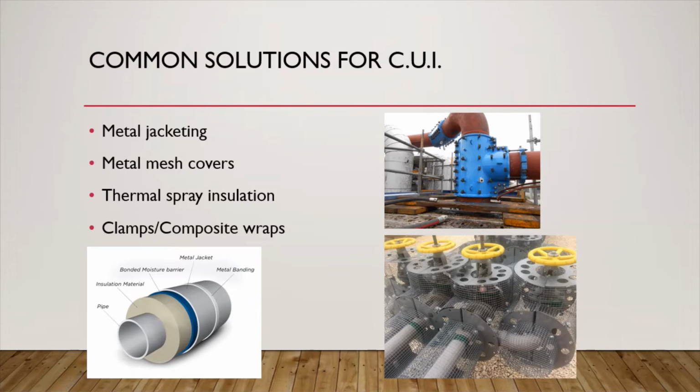Thermal sprays to coat the piping like a paint job are also available to use, but are significantly more expensive and are only used for more justifiable occasions. If the section of piping cannot be brought out of service for maintenance, then clamps, leak boxes, or wraps are usually installed to mitigate any leaks that formed or might be forming.